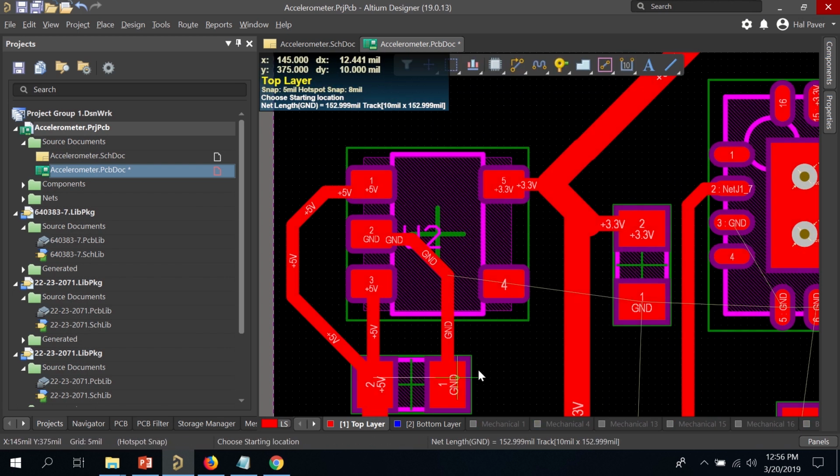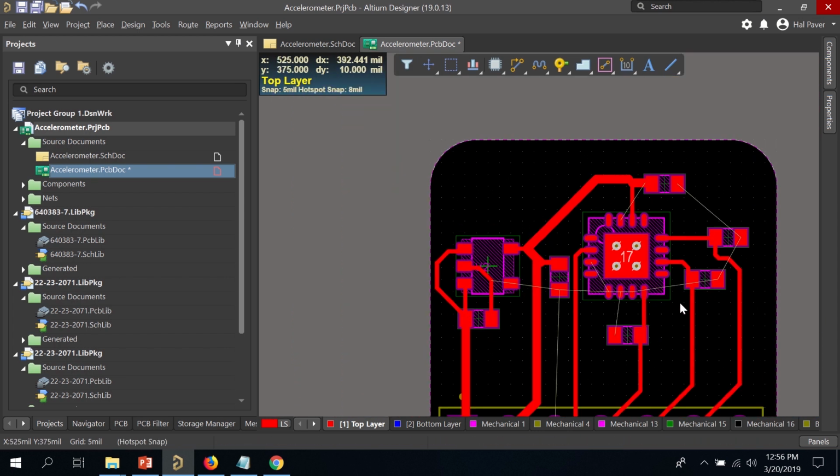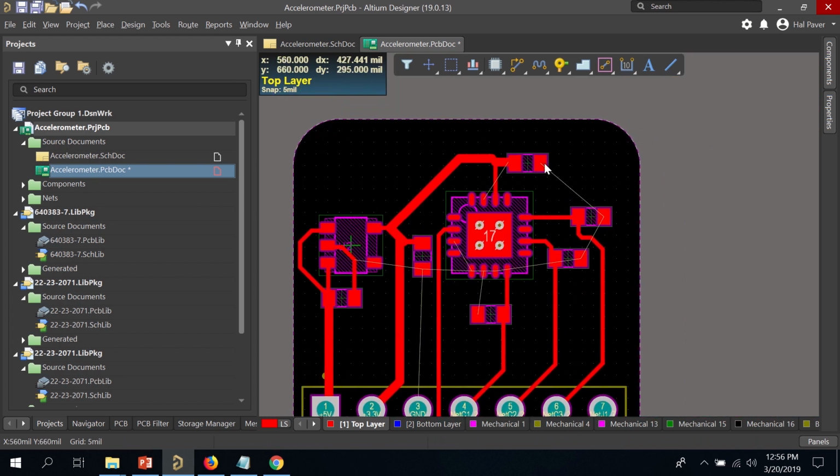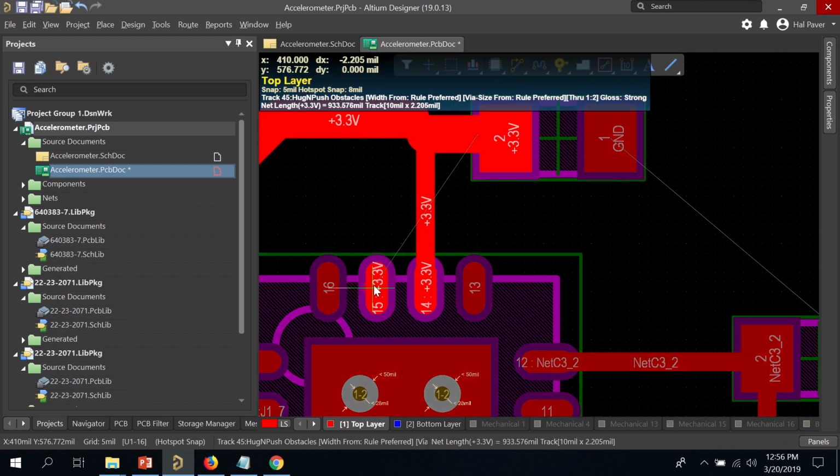Be careful when you route under a component. If you need to later delete that trace manually with a razor blade, it will be kind of difficult. Also, when you're routing two pins one next to one another, it's a good idea not to route it in such a way that you won't have access to that trace in case you've made a mistake. So bring the trace up and over.